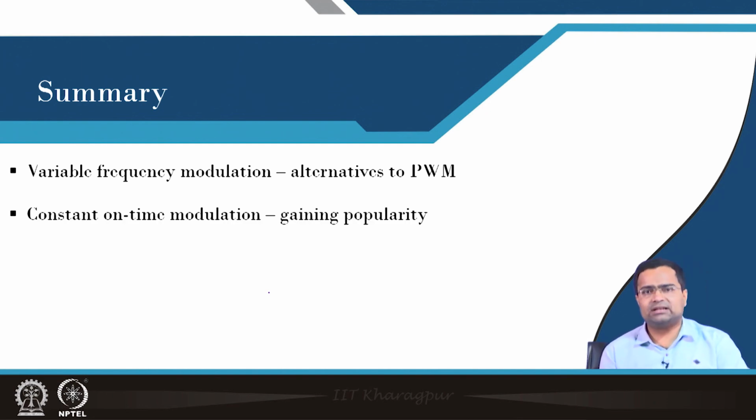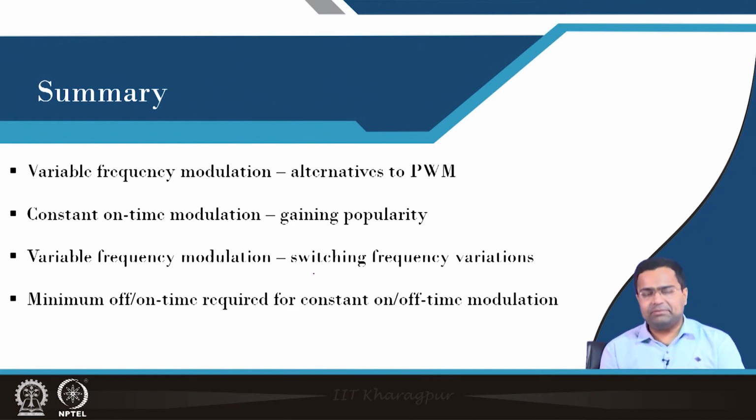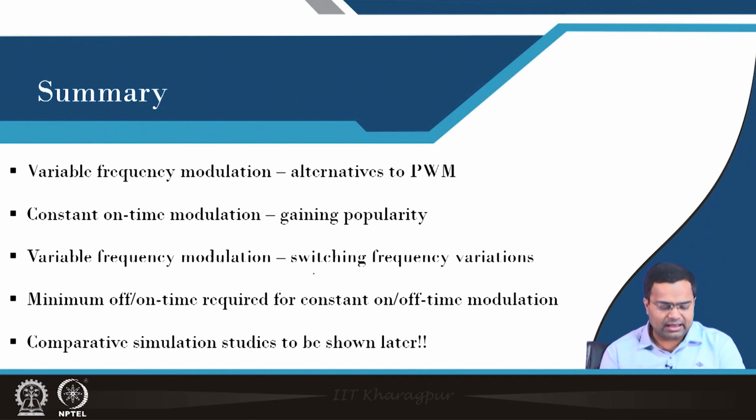So, with this summary, variable frequency modulation we have discussed is an alternative to PWM. Constant on time modulation is gaining more and more popularity in applications. One of the problems of variable frequency modulation is the switching frequency variation, and a minimum on time and off time is required whether you take constant on time or constant off time modulation. Comparative simulation studies will be shown later.